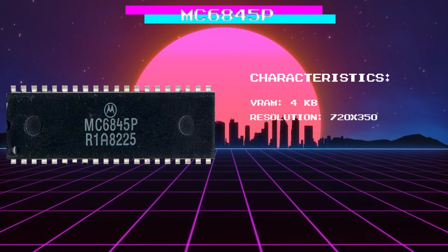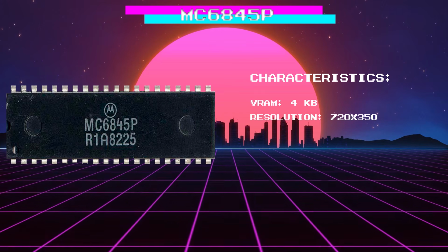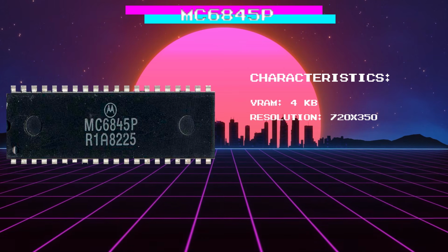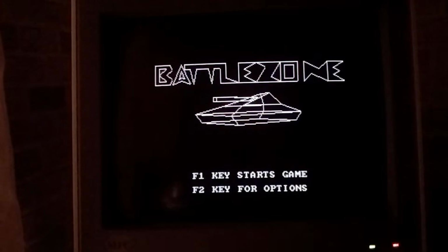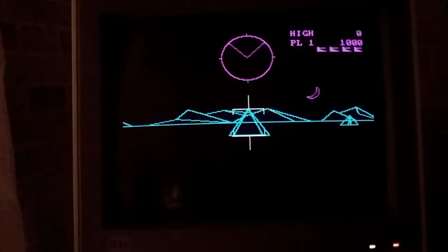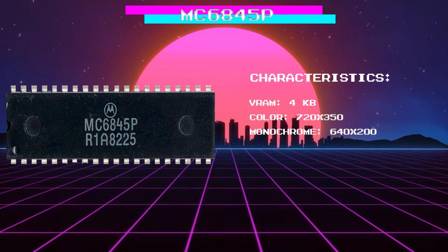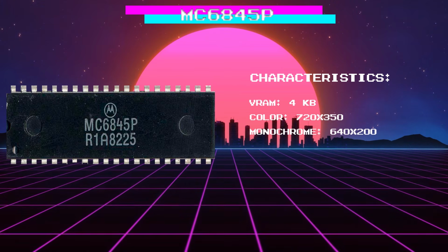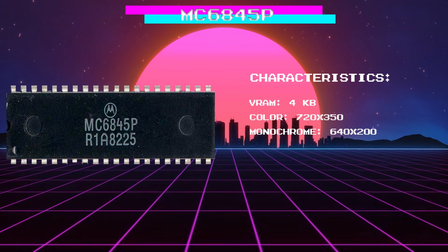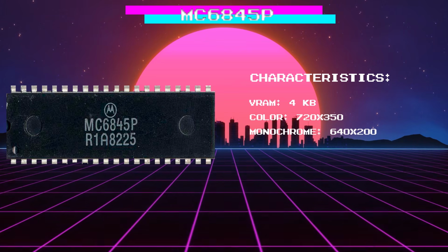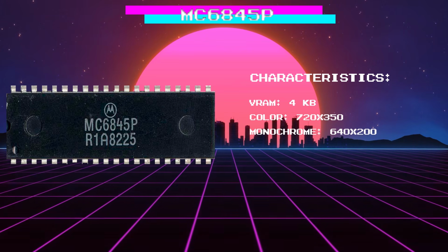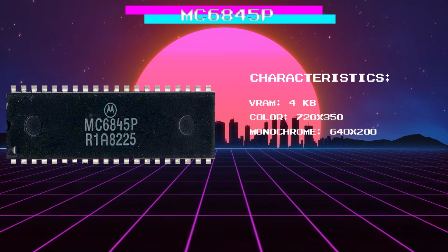The CGA video adapter was considered the opposite of MDA. In addition to working in text mode, it could function in graphics mode. Both black and white and color images were supported. It was essentially the first card with support for 16 colors. The core was the same Motorola MC6845 chip, but the memory was 4 times larger. In the operating mode with a color picture, the maximum resolution was 320 by 200 pixels, and with monochrome